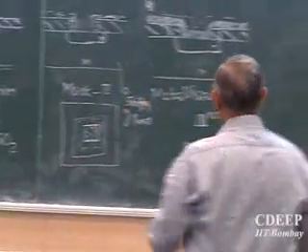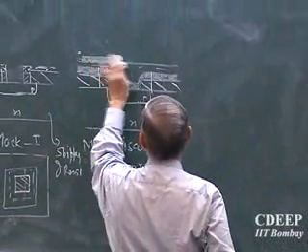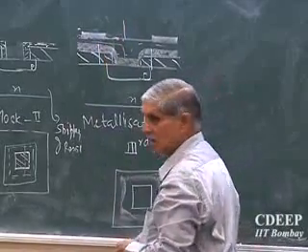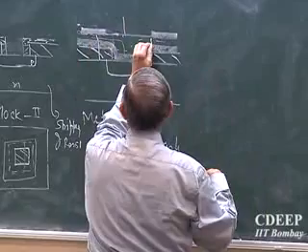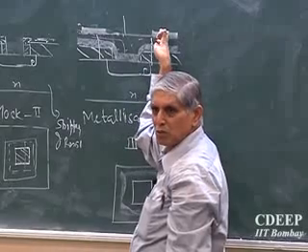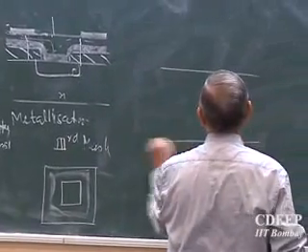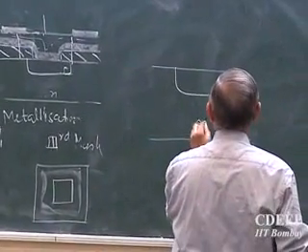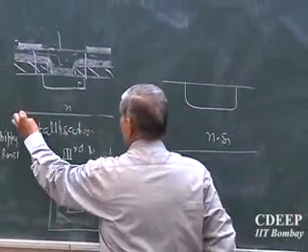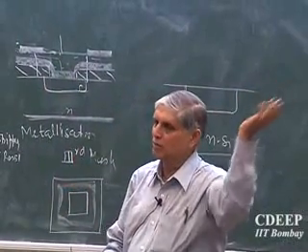Okay, clear. So if I now put this mask on this, which has black portions here, black portions here, black portions here, the light will go from here and will harden the resist in this region. Then I will etch out the aluminium from the rest of the portions. Is that correct? Then I remove the resist and I have a final diode with me. This is my P, this is my N silicon. And in the same way, I use the back contact full size. During the first evaporation, I will immediately invert the wafer and coat the full wafer from the back side.